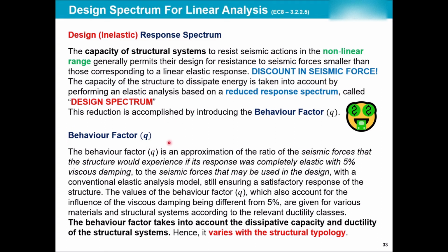Using a behavior factor, we reduce that acceleration to a lower acceleration, depending on whether the building is a stiff building or a flexible building with different values, and you will design your building for a lower acceleration.